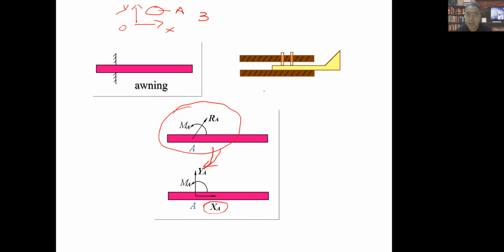So we can think of it as a fixed support. Am I right with this English word? In plane, right? In plane. It will have three kinds of reaction force. I hope you guys can totally understand and remember how to draw a constraint like this. It's three reaction forces. You should draw like this. And then we will use some equilibrium equations to find their real values, right?